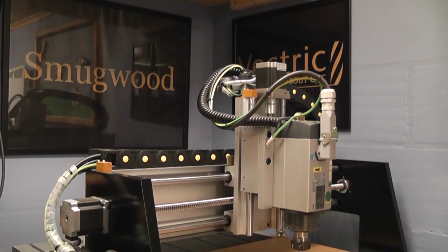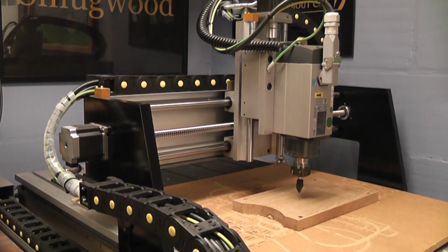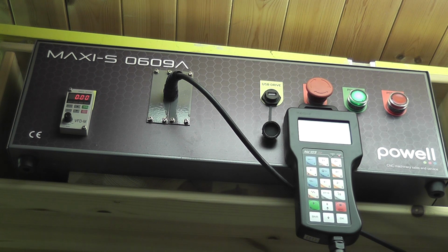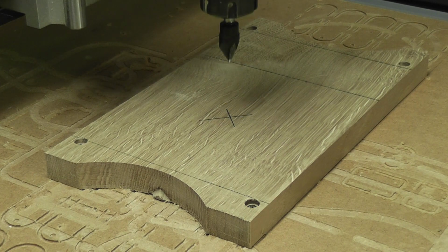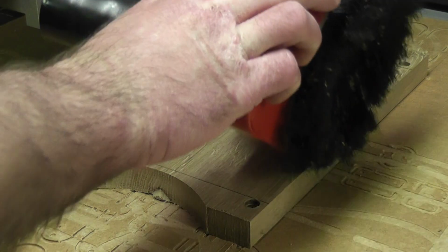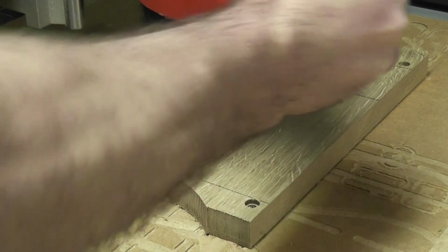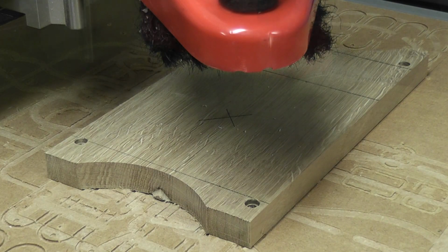So at the CNC I've screwed down a piece of 22mm oak to a sacrificial piece of MDF. It takes just seconds to upload the file to the CNC and it's ready to go. The 60° V-bit cutter is secured into the collar and the centre of the piece all marked up and all X, Y and Z programmed into the machine. The dust shoe goes on and it's ready for engraving.